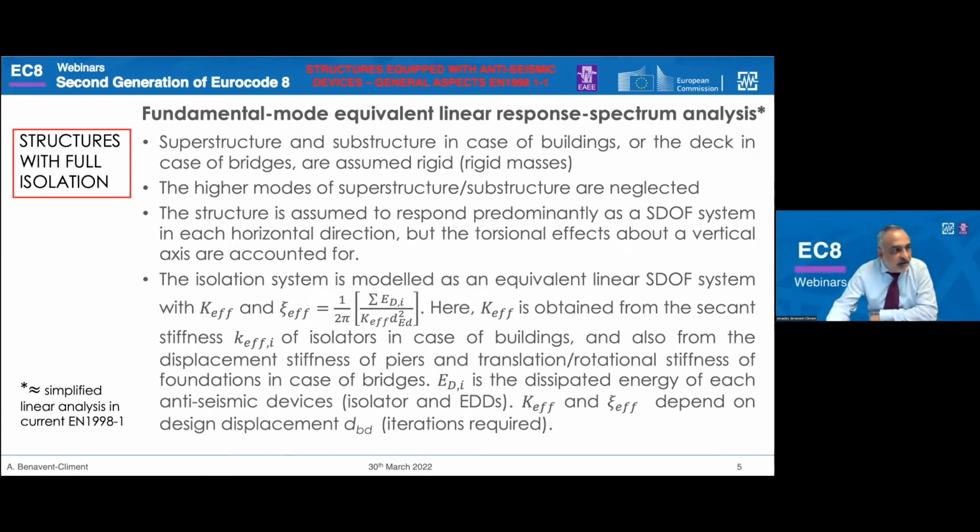Now let me explain the main features of each method in more detail. The fundamental mode equivalent linear response spectrum analysis is similar to what is called simplified linear analysis in the current Eurocode 8. In this method, the superstructure and the substructure in case of buildings, or the deck in case of bridges, are assumed perfectly rigid, as rigid masses. In this case, the higher modes of the superstructure and of the substructure are neglected.